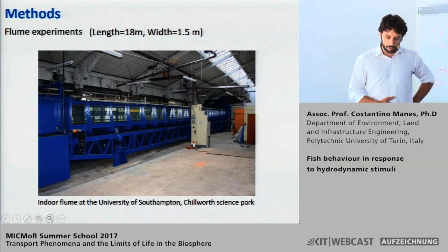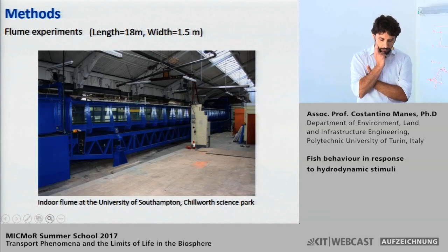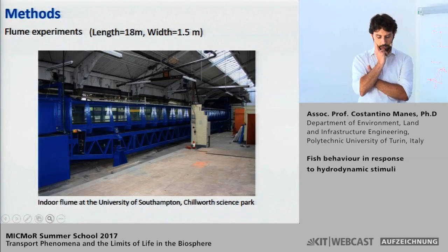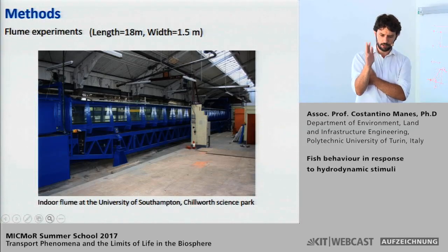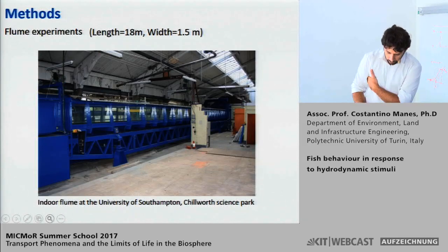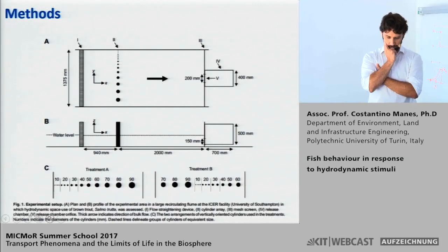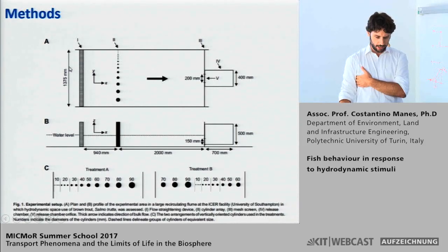To test this hypothesis, we decided to do some flume experiments at the University of Southampton. There is this large flume, which is well suited to do some fish research. The flume is long, 18 meters I think, and roughly 1.4 meters wide, not exactly 1.5, but fairly large. We have selected a test section of the flume, roughly 3 meters long, which was bounded upstream by a honeycomb,